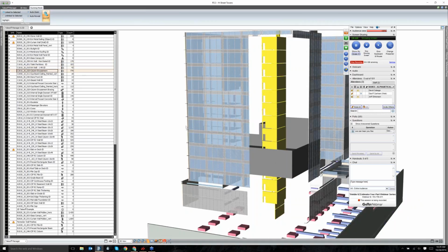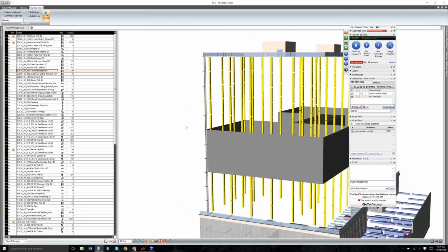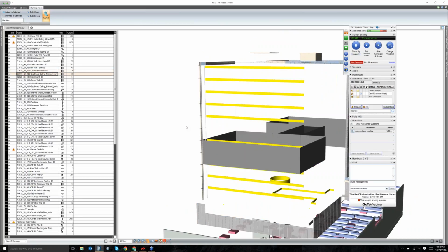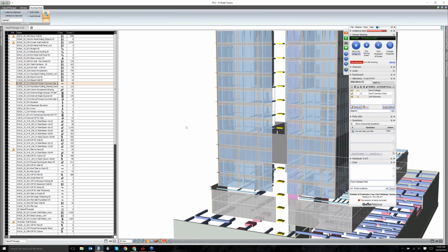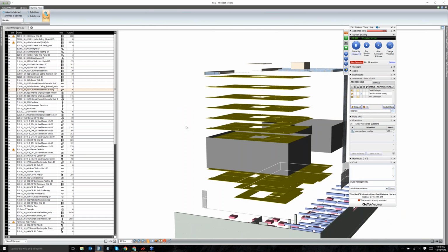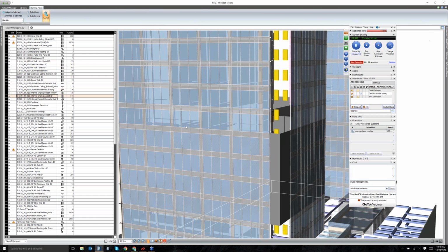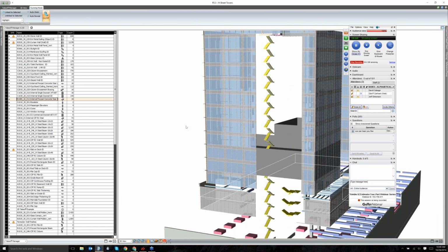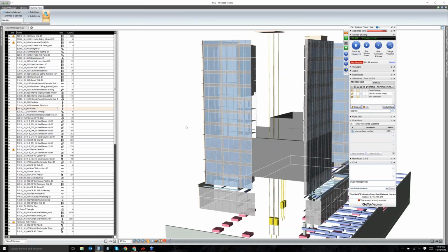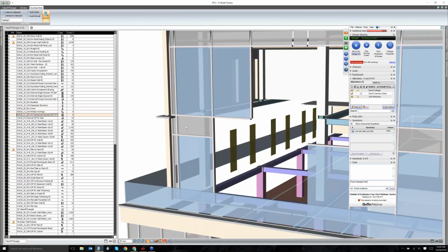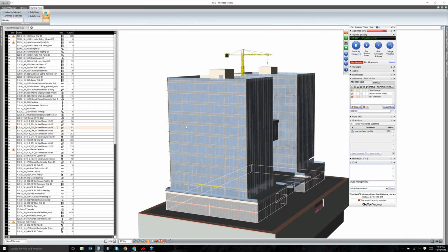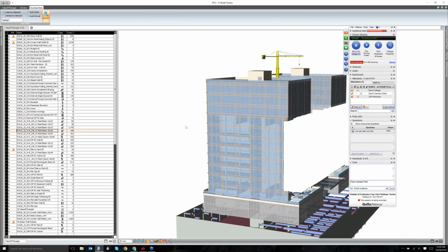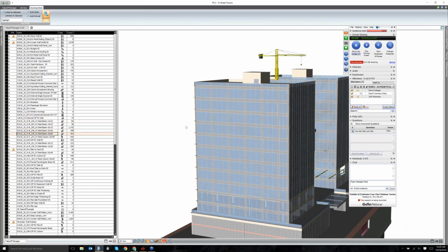So now I'm looking at my interior walls, my column encasements, glazed walls, and we can go down the list. We could do the opposite as well and make our selected element translucent, but I think making everything else around it translucent actually makes it a little more powerful.